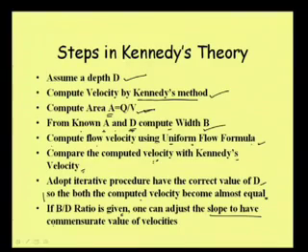After Kennedy's theory, the next theory that came is Lacey's regime theory. We just gave the name earlier in the last class, and discussed how it was originally developed, so we are not going to that part. His principle is the regime channel. It is similar to having a critical velocity, but what he suggests is that a channel of a particular size can be regarded to be in regime condition.